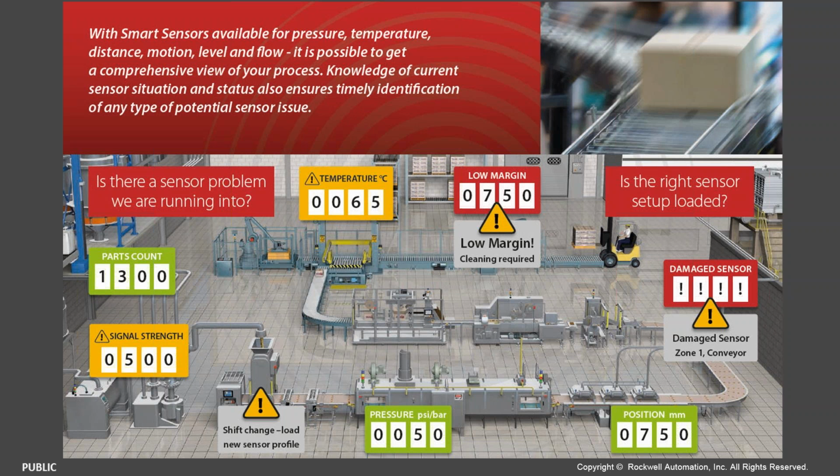With a traditional implementation, you would not know if a photoelectric sensor was too dirty to operate properly, or an inductive sensor was damaged. There was no way to know until we had a production issue, until the sensor failed and the line stopped. And then through extensive troubleshooting, eventually we track it back to a dirty sensor. This results in a lot of valuable time wasted, which would ultimately be linked to production loss. Now an IO-Link enabled photoelectric sensor can tell the control system that it is dirty before this causes any production issues.